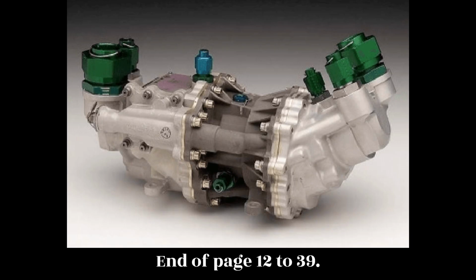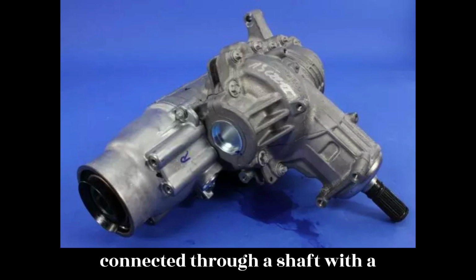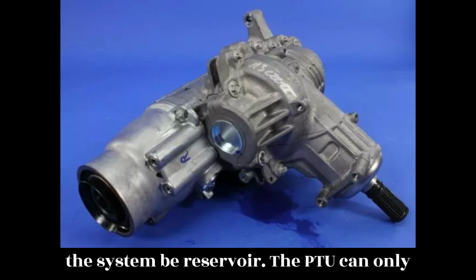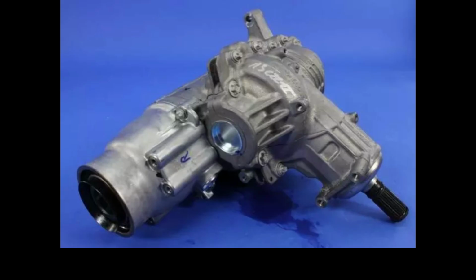End of page 12-39. The hydraulic motor of the PTU unit is connected through a shaft with a hydraulic pump that can draw fluid from the System B reservoir. The PTU can only transfer power and cannot transfer fluid.